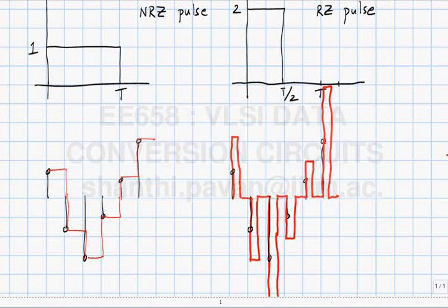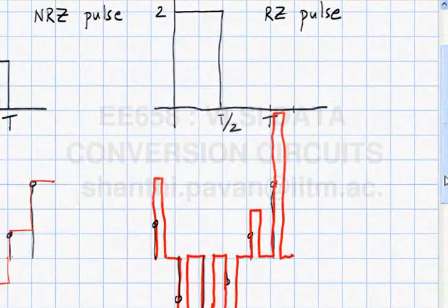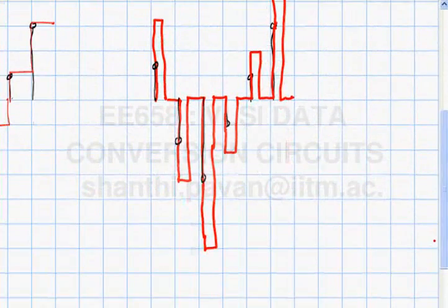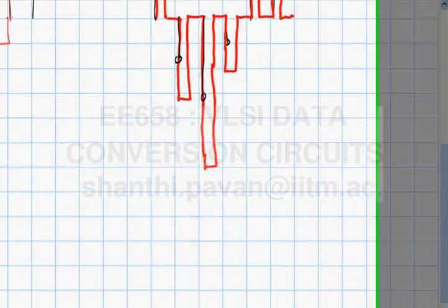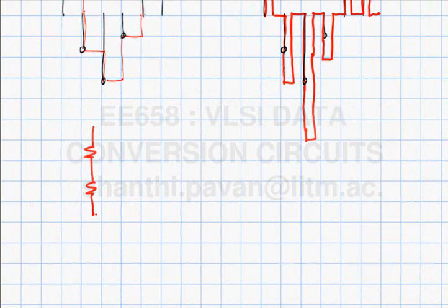You certainly do not want to do the following. You do not want to generate an impulsive DAC and put a filter like this, with an impulse response like this, which is not realizable anyway. Okay. The simplest thing to do is what was suggested by one of these chaps. Let's say you've already seen an example of a DAC, and where is that? That's in the resistor string of the flash.